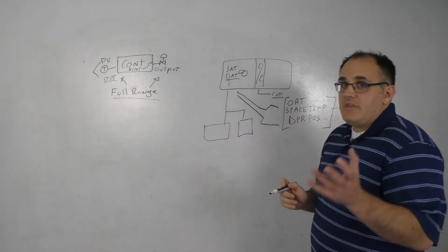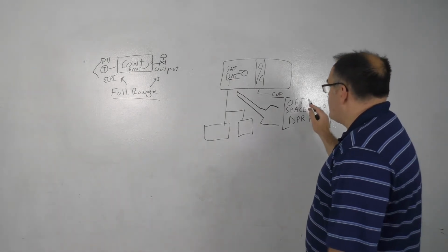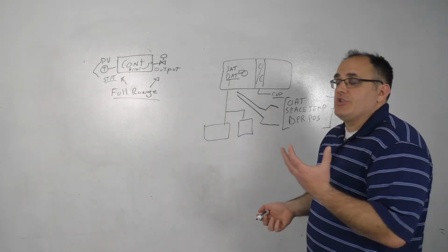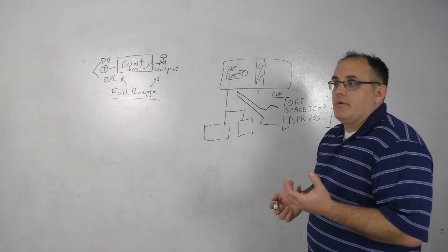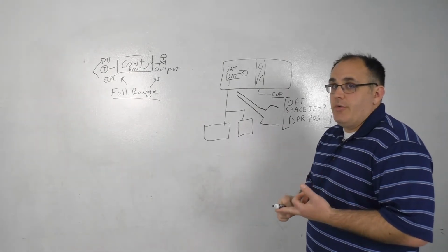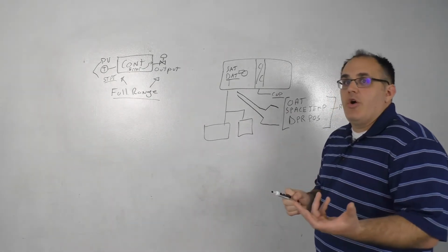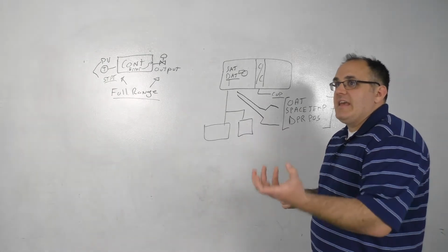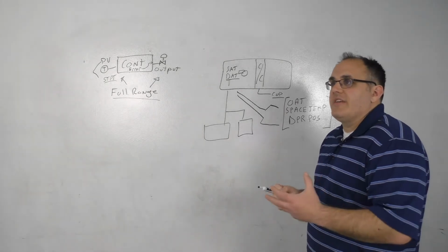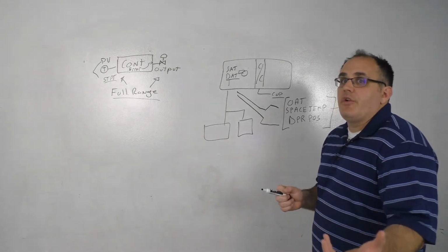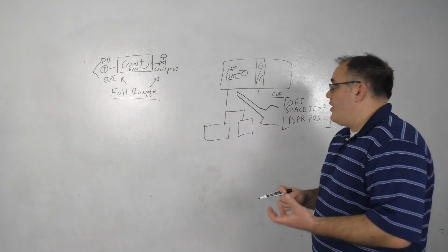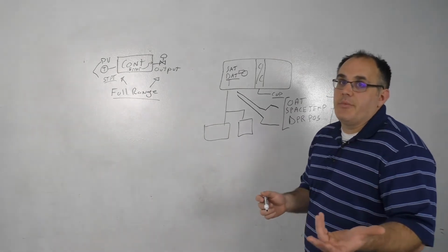Now, outdoor air temp, in my professional opinion, based on my experience, is the worst way to reset almost anything. Outdoor air temp does not account for actual load in the spaces. And when I say load, I'm talking either the heating or the cooling that is required, so either the removal or addition of BTUs into the space, or out of the space in the case of removal.